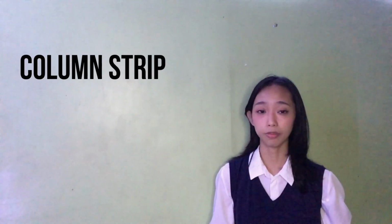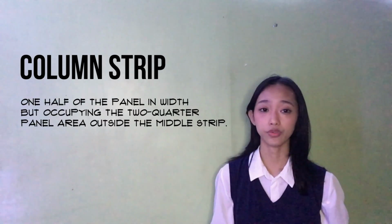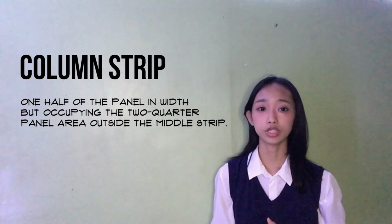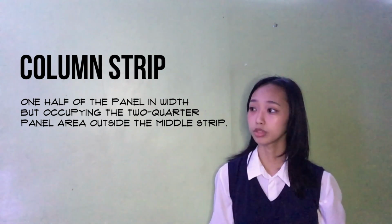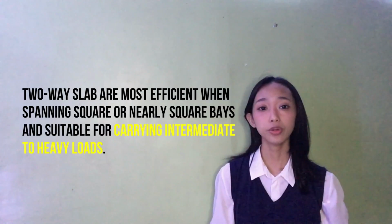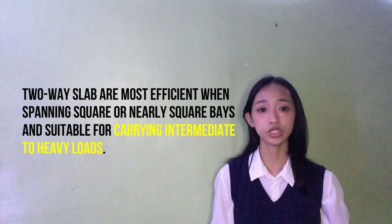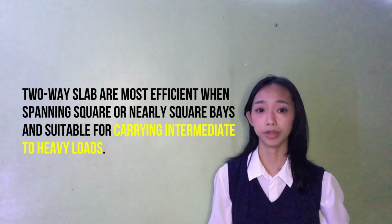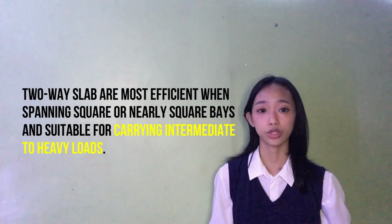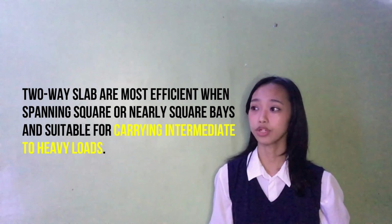The second one is the column strip. This is also 1/2 of the panel in width but occupying a quarter panel area outside the middle strip. Two-way slabs are most efficient when spanning square or nearly square bays and suitable for carrying intermediate to heavy loads.